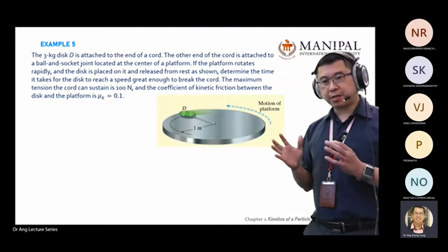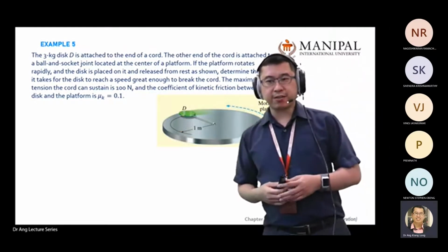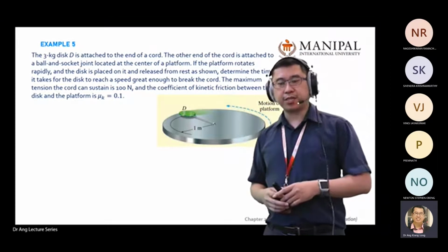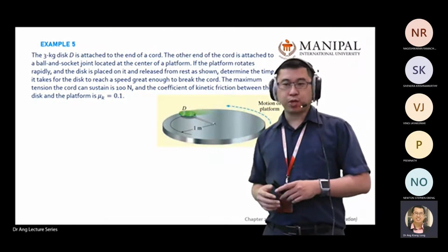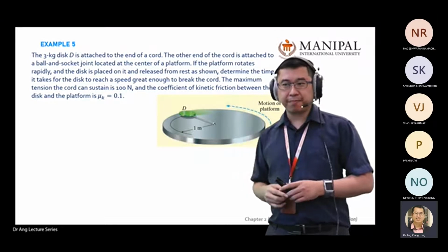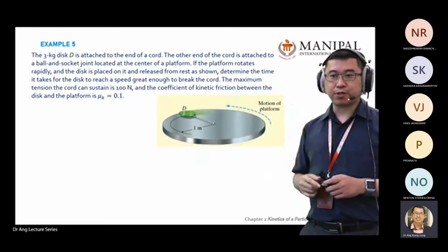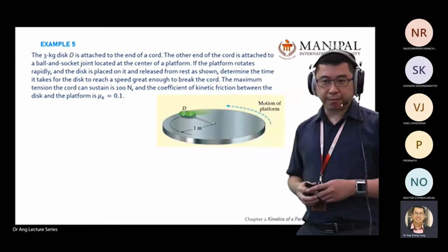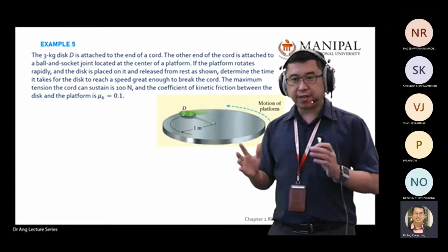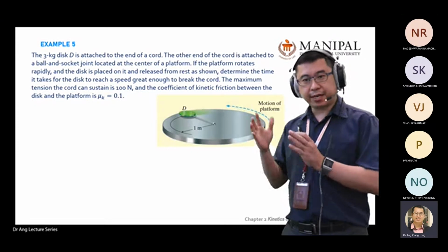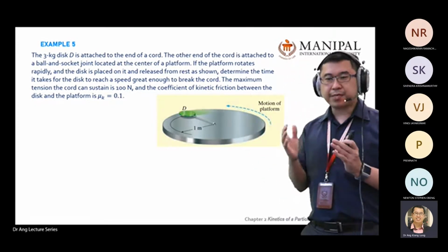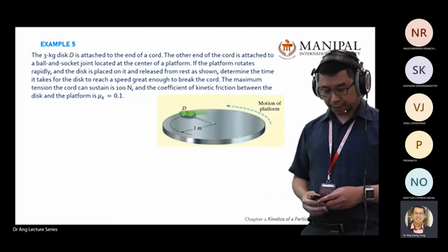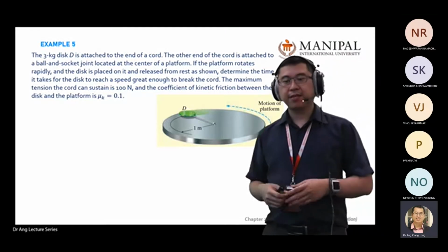Okay, it might sound a bit complex here, but you don't need to scare yourself. You just look at a normal object. Recall the standard procedure when you solve a chapter 2 question. Remember, you always need 2 diagrams. And you only need to solve one equation: F equals ma. Remember, 2 diagrams, solve F equals ma. Then you look at the question, slowly develop the free body diagram and kinematic diagram. Find where the missing parameter is from the equation itself. Then you slowly solve. Okay, so basically build diagrams, solve F equals ma.